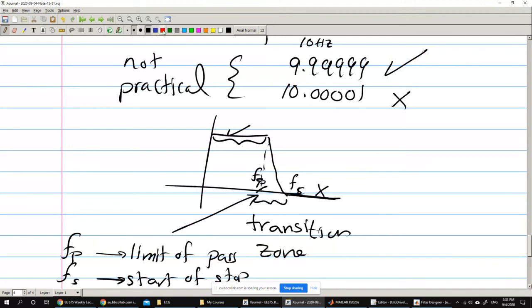The second thing about the practical filter is that usually in the pass band, it's never flat like this. It's never like 1. It can actually have some variations around 1. And basically, instead of having just 1 here, you allow it to change here within a certain limit.